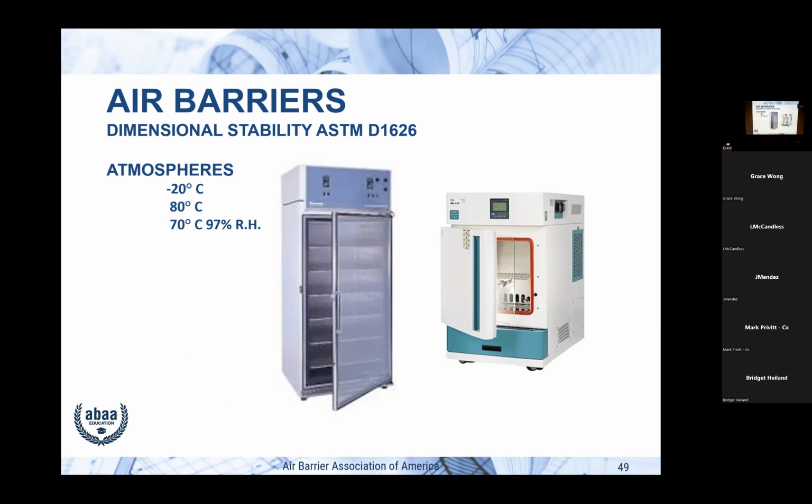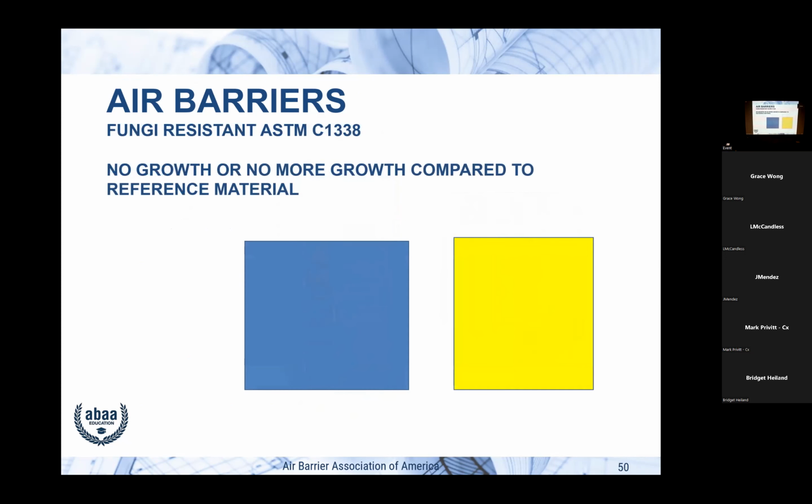Actually, hot and humid will have the biggest impact on what happens to the material. And most materials will expand and then shrink. So that's why the 28 days is important. Some people do it for 7 days, but has it gone through the whole thing, whether it shrinks and expands or expands and shrinks? That's why we require 28. And that's in most material standards out there.